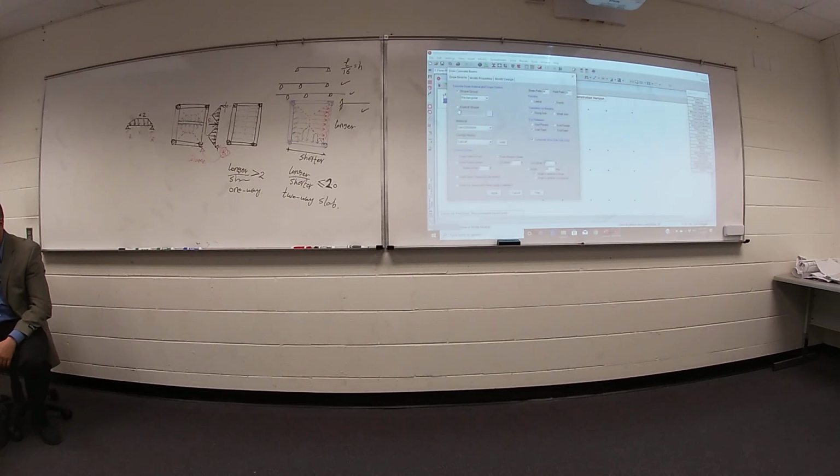Is your cross section rectangular? Maybe a different shape. So we can use explicit shape and you can define it from this icon. What is the depth? 30 feet, I'm sorry, 30 inch. What is the width? 16 inch. Okay, apply, go ahead. Draw from here to there.